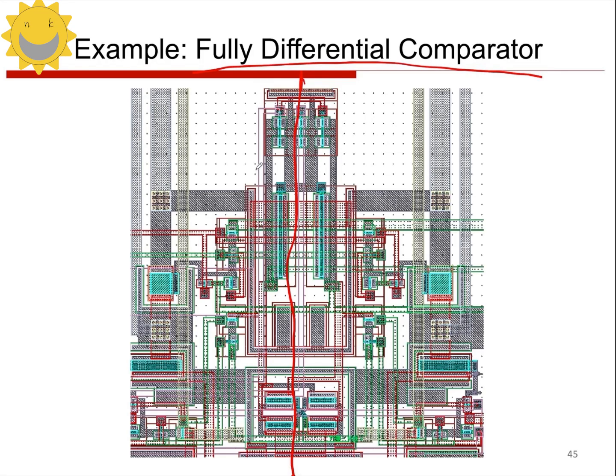When you fold it left and right, they almost overlap perfectly. This creates a very good symmetrical structure, meaning the layouts on both sides are identical. This is beneficial because in our differential circuit, it effectively suppresses common mode noise. It will effectively suppress common mode noise or interference, as well as improve matching.